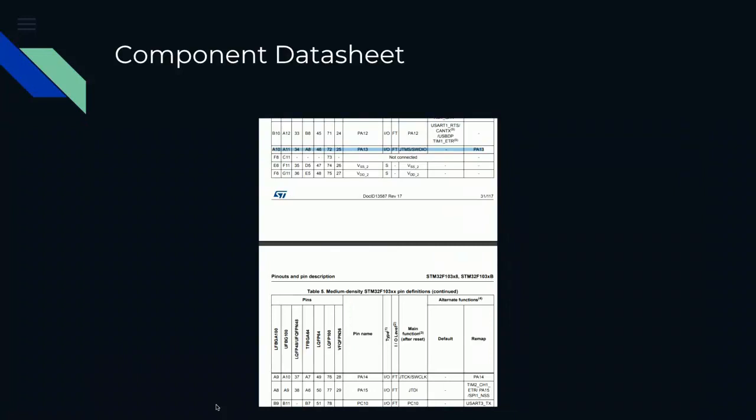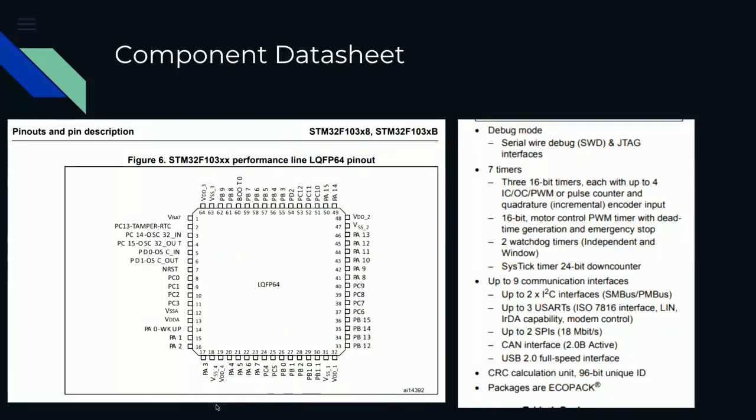If you continue on that device, you can see where, for instance, the program pins are present. For instance, PA13 would be on the top left. You could easily identify where it's supposed to be and try to track that trace.